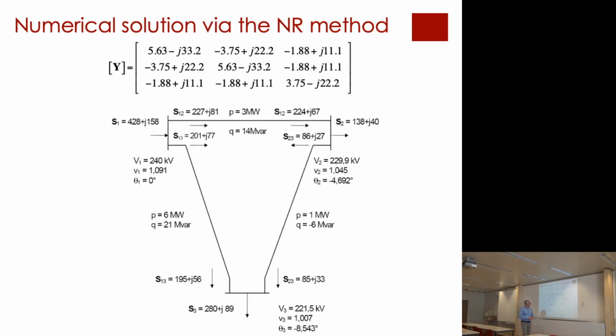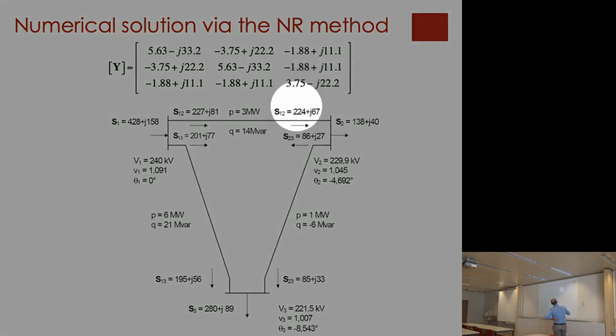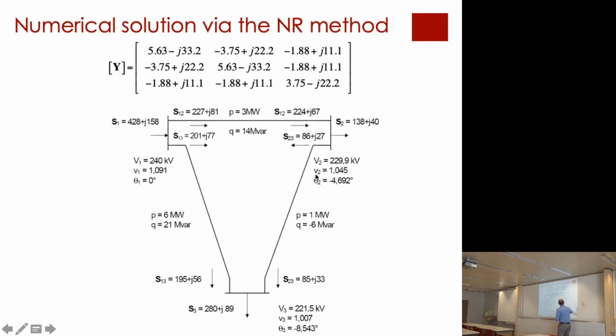And this is the solution of the load flow. Here you get the S2 and the S3, which are essentially what you fixed. And these are the voltages in amplitude and in phase that you are getting. Amplitude in actual values and in per unit, and the phase.